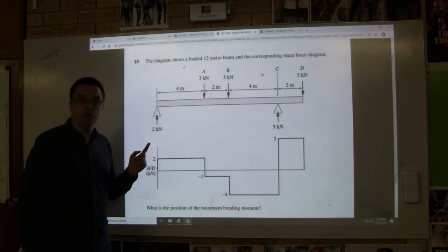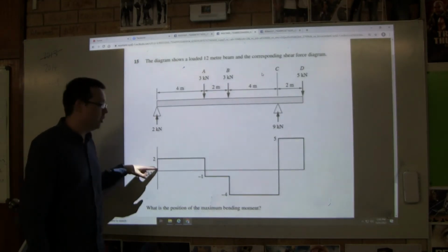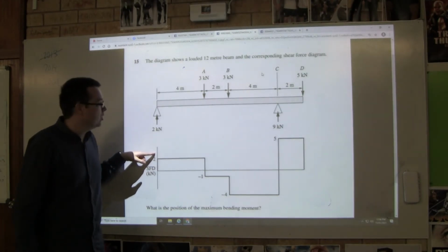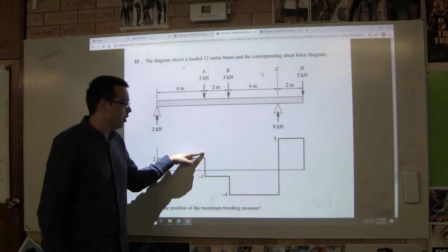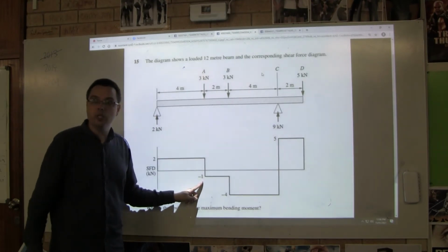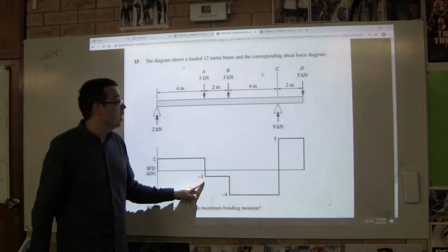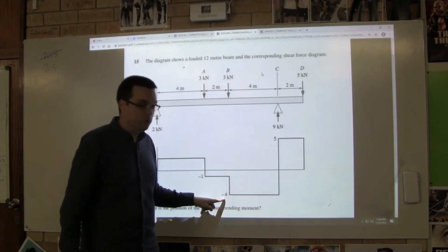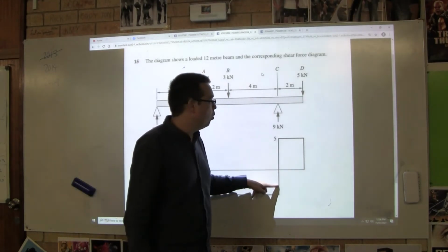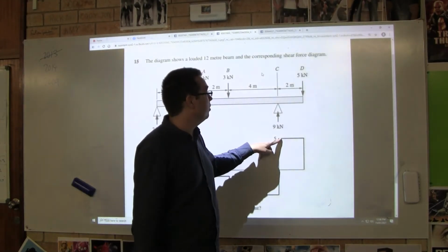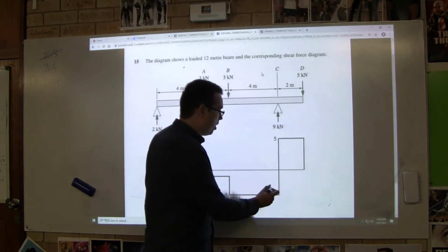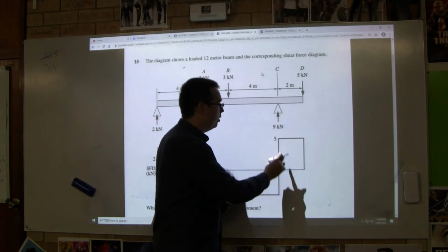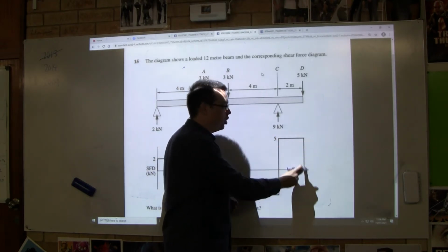Once upon a time, there was a beam. And it started off by, like the roller coaster, going up 2 meters. And then it went across. Nothing happened. And then there was a drop, 3. It went 2 minus 3 is? -1. It went across. Nothing happened until 3 dropped down again. -4. And then whoosh! It went up. All of a sudden, 9. It went from -4 up to 5. And then it went across and then went down.